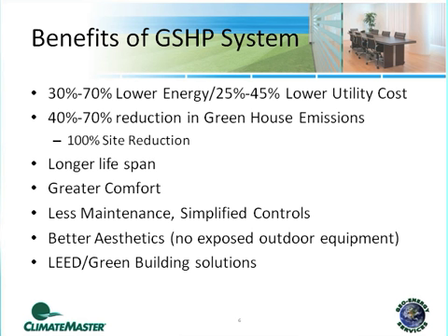Now, I will caveat that to one level. We still have to deal with ventilation air, outside air. And when we make those considerations, we typically may still have some equipment mounted outside that deals with the ventilation or fresh air component of this. So we may not be able to completely eliminate all of the outdoor air equipment. But for 90% of the projects, we can still work around that and bring the ventilation equipment indoors as well.